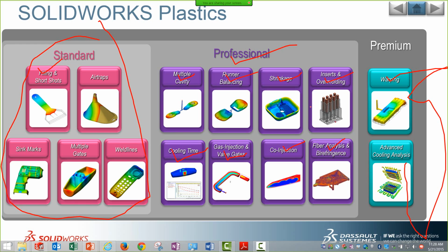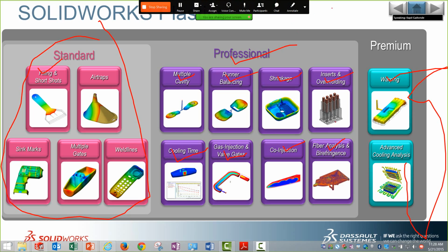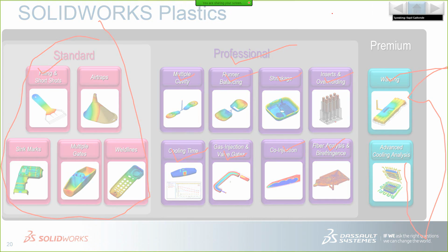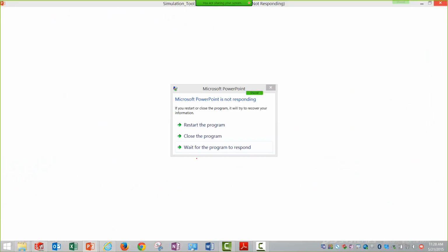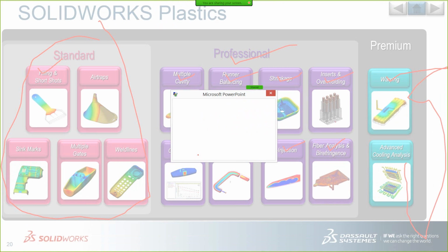I can also know the injection pressures, etc. Using these I can derive certain mold details. Mold designing, such as creating the parting lines, can also be done in the CAD part of it, and our CAD module does have some capabilities by which we can do that.